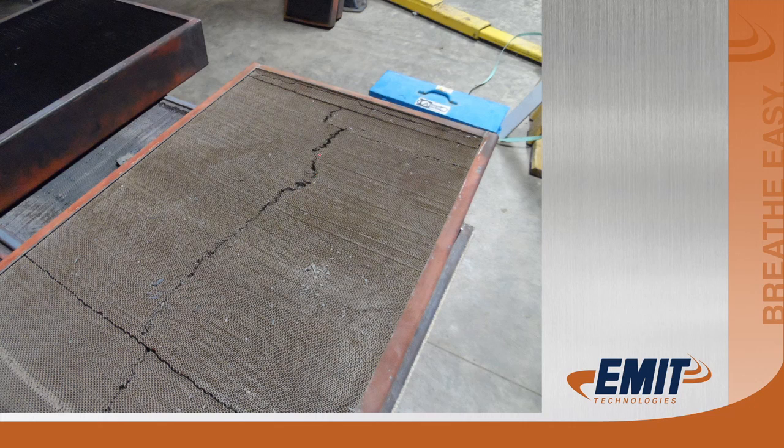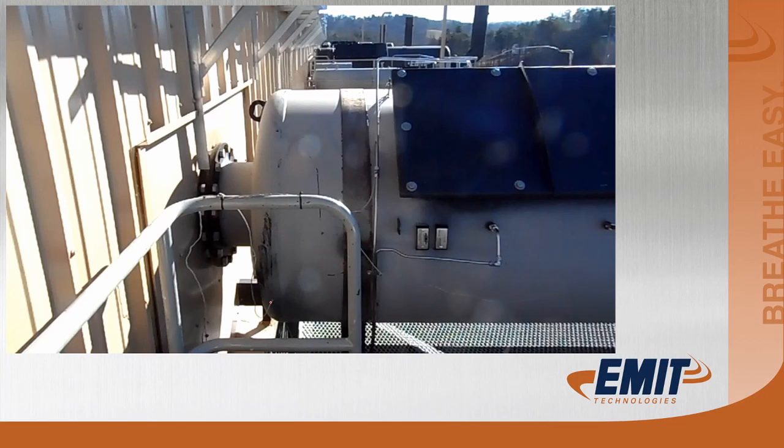You won't damage a catalyst right away at 1250 degrees, but it doesn't take long, and after several cycles this foil expands and contracts, and you can see this one kept contracting further and further until there were cracks in it.